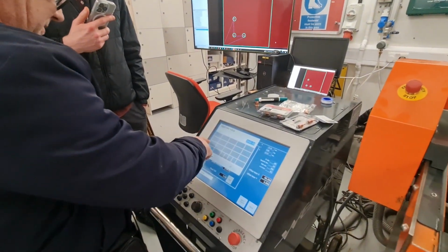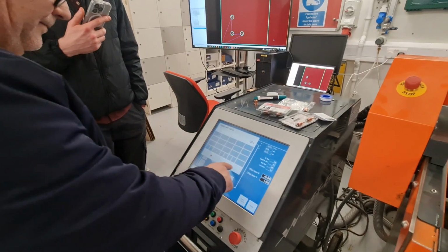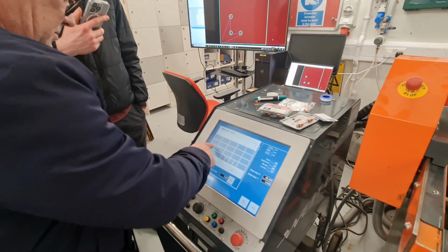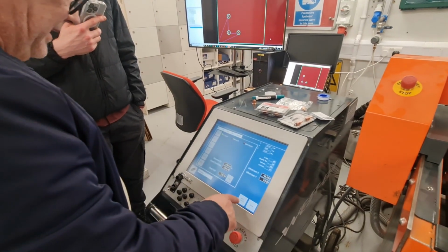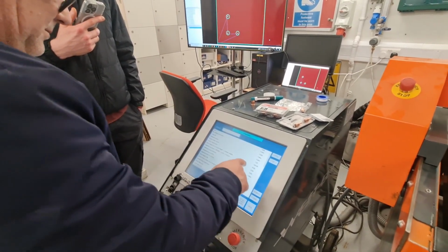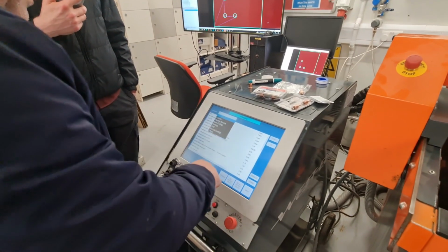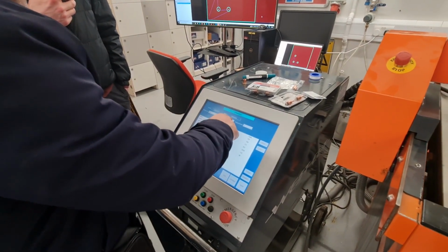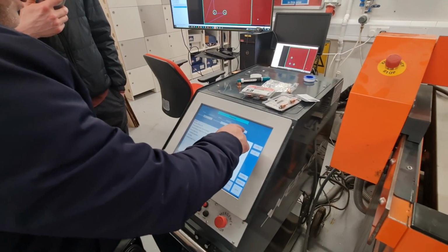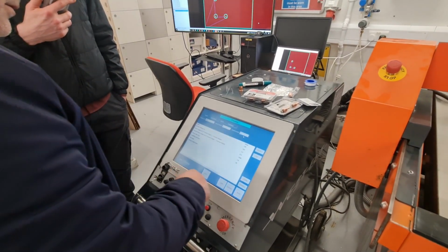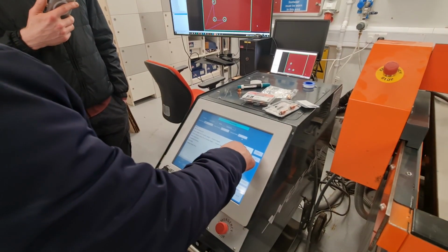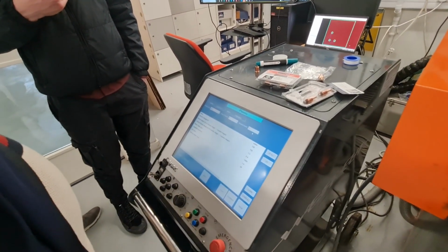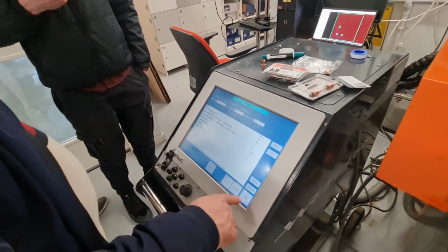Now the feed rate was 1800. So I have to change this one to 18. And the voltage was 130. I bring that from the database, okay? So the arc voltage is 130, the feed rate is 1800. That's where I bring these numbers.